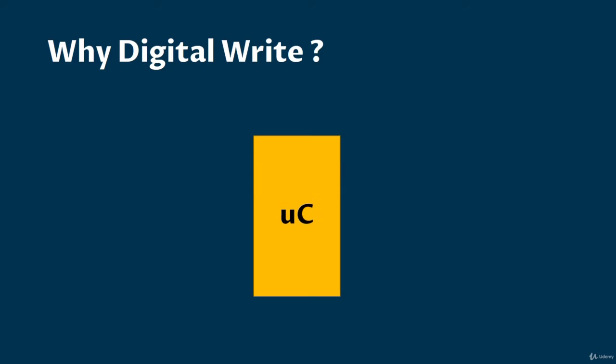Let me tell you, there are a lot of uses. Why do we need digitalWrite? Through this function, the controller on the Arduino Uno board can control outputs. I'm giving you some examples. Displays can be controlled using digitalWrite, like 7 segments, LCD 16x2, graphic LCD, etc.